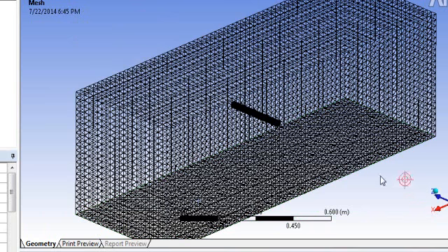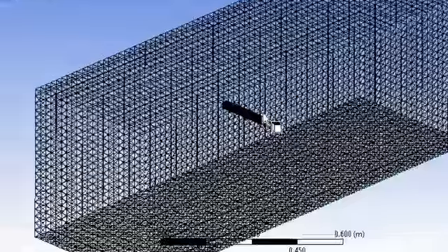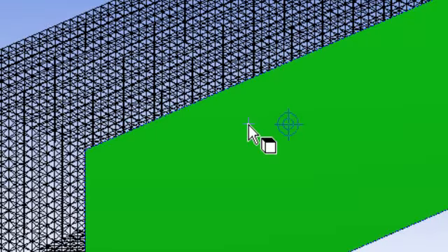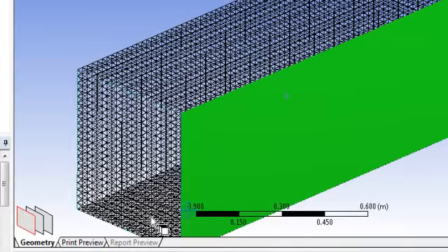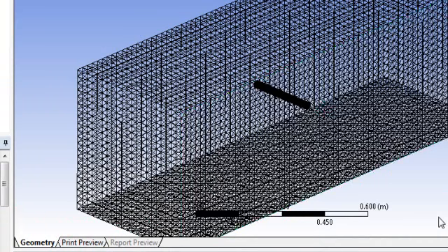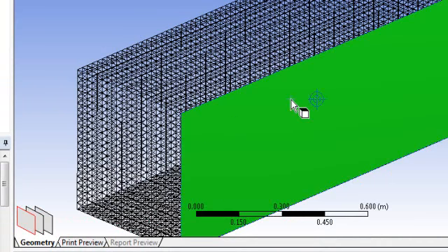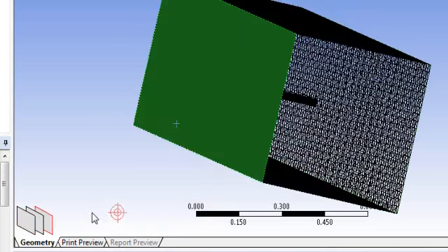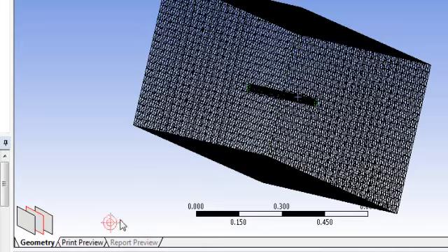All we have to do is take our cursor to the top of the cylinder and select this. If we select here, you have only two planes. But if you select at the top of the cylinder, you have three planes. The first plane is this plane, obviously the third plane will be that plane, and the middle plane will be our cylinder.